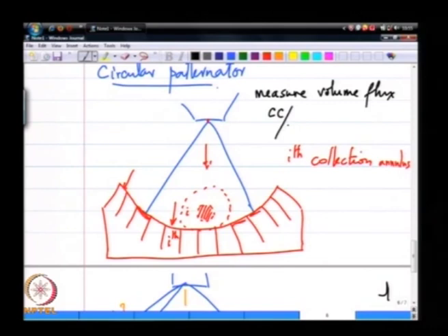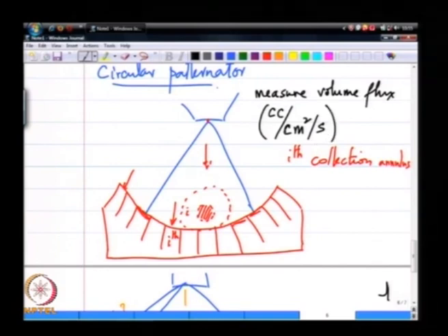So, it is in this quantity Ai that the problem arises. If I have 20 annuli across the circle, and if I want to calculate Ai for the ith annulus, I use the geometry of that annulus: the inner radius and the outer radius. I am essentially assuming that the flow is entering the annulus nearly perpendicularly, which will be the case if I have them on a circular arrangement. If I have them on an inline arrangement, it does not necessarily be the case.